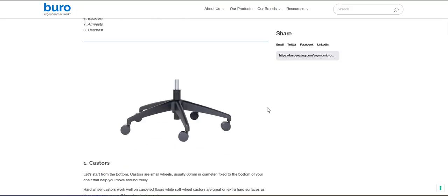So let's start, for example, with the casters. For the casters, you can find that we are going to have these wheels, which are made of plastic. We can talk about how they were manufactured if you're going to focus on that. But in a real life scenario, these will be something we're going to buy. Okay, so the casters usually are going to be an off-the-shelf item. You don't have to manufacture it. But if you would like to add a discussion on how these casters are manufactured, it's going to be very simple. We're going to make 2 wheels, with a shaft in the middle, we're going to have the pin and the support, and then we're going to assemble it.